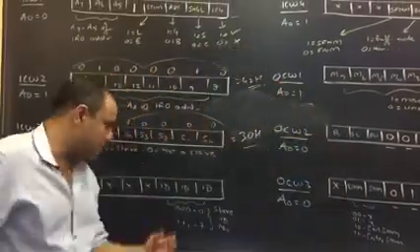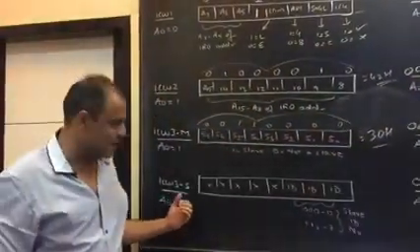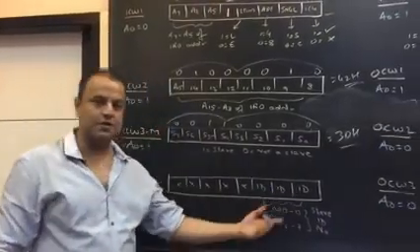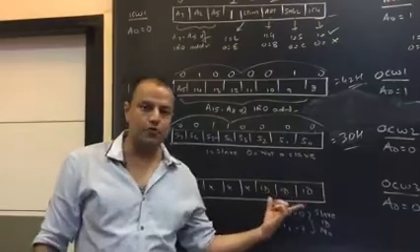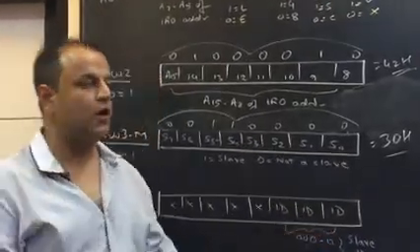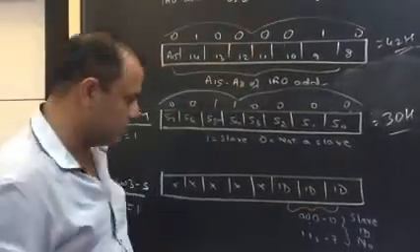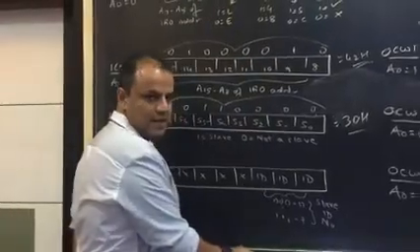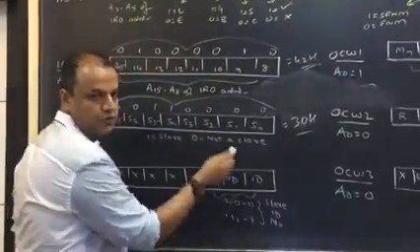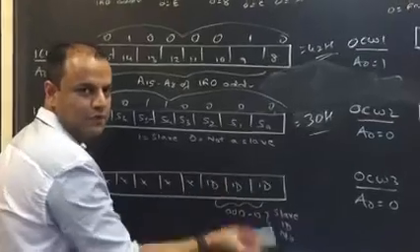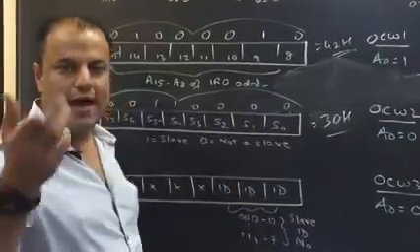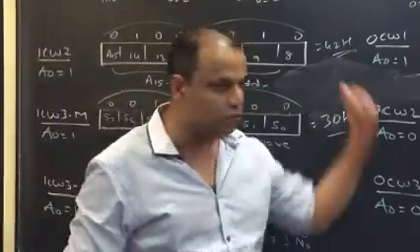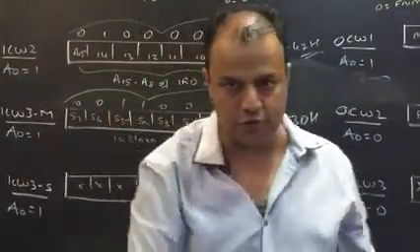That is why ICW3 for the slave has only 3 bits which are useful. The remaining bits are garbage, keep whatever, it doesn't matter. The 8259 will not look at them. It knows the ID number will be there in the last 3 bits. So for the first slave, which was right at the top, connected on IR0, its slave ID will be 0, so you'll be giving 000. For the next slave, you'll be giving 001. For the last slave, you'll be giving 111. Whom do you give this command? Every slave. Remember, you have to do this whole procedure for every 8259.